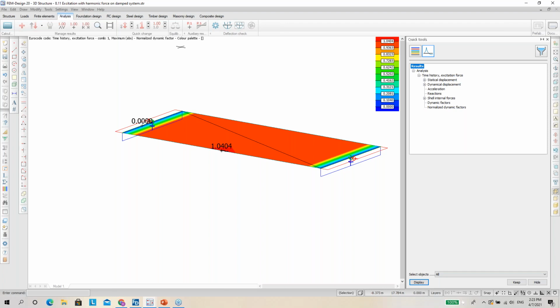Something worth mentioning is that the first feature introduced is a linear time history analysis. So it's not non-linear. That means that crack analysis or second order analysis and so on and so forth will not work with it at the moment.